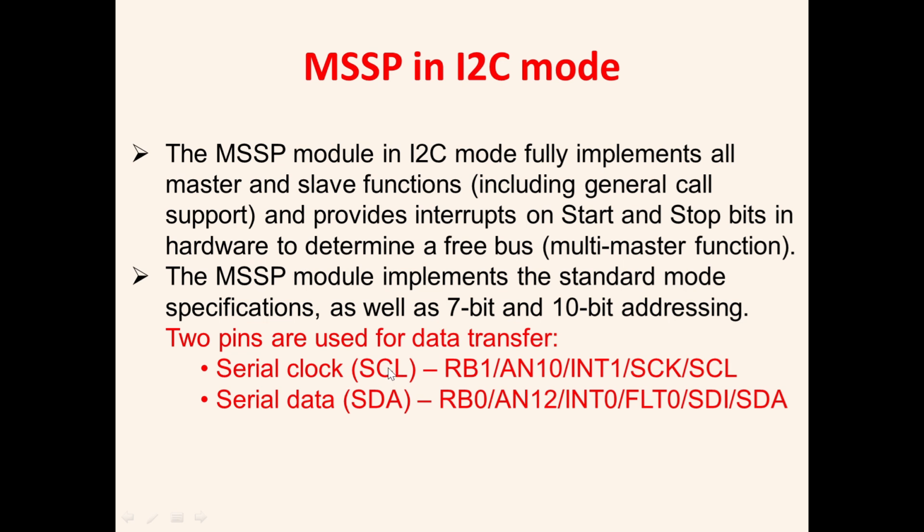When you communicate with your peripheral in SPI, the communication is only taken care of between master and slave. There is no kind of acknowledgement in SPI, and no kind of start and stop bit in SPI. In short, the I2C protocol will always provide start and stop bits along with the data, and every time it will generate an acknowledgement.